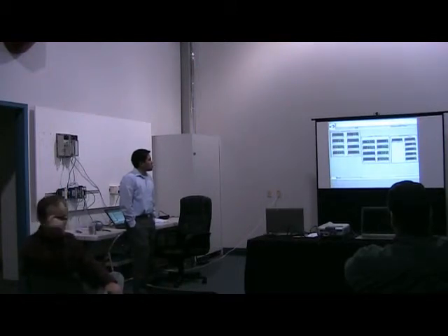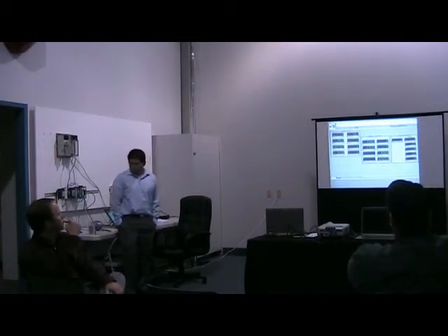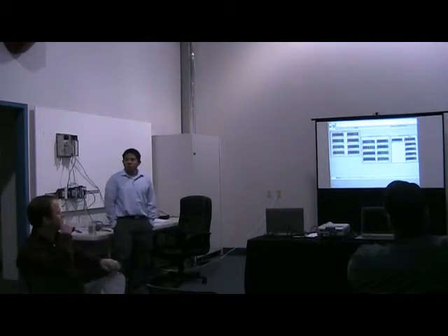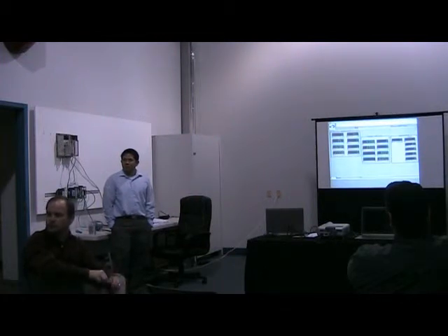One of the things I've recently done on HART: if you ever pick up the handheld calibrator, there are a ton of buttons on them nowadays versus the 9 that you had back 20 years ago. I'm dating myself, by the way. You have to be very specific on what you're looking for and how you're looking for it, because button sequence is important, especially when you're troubleshooting. The software on a host application is easier to set up than it is when you're troubleshooting out in the field.